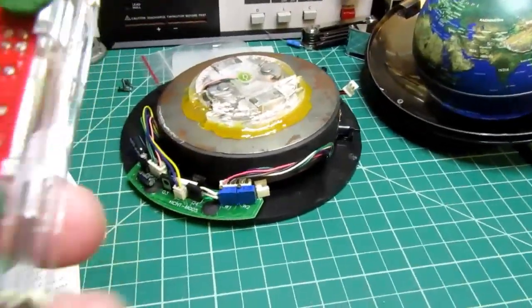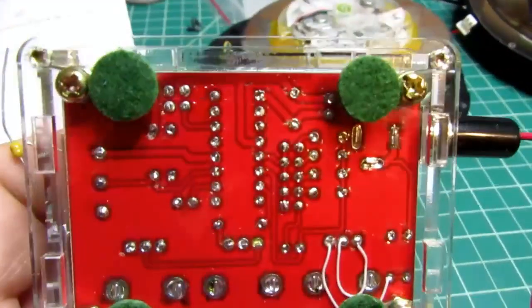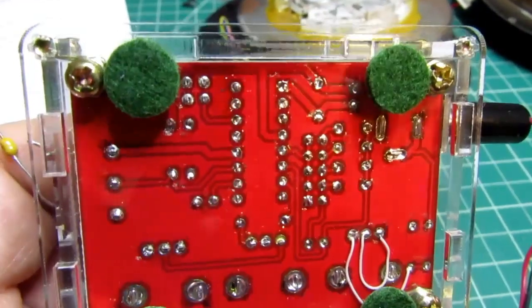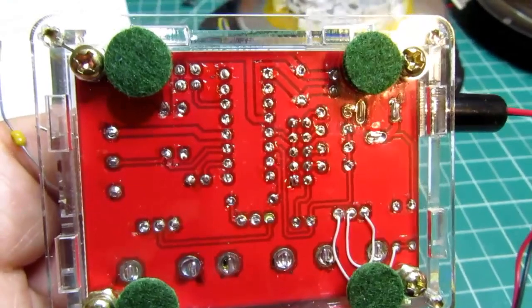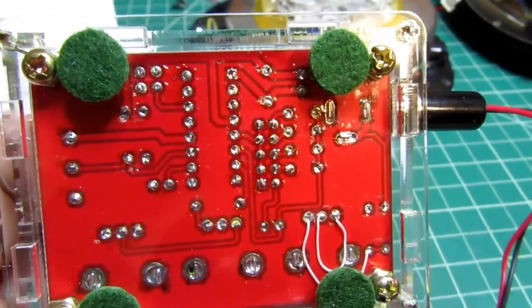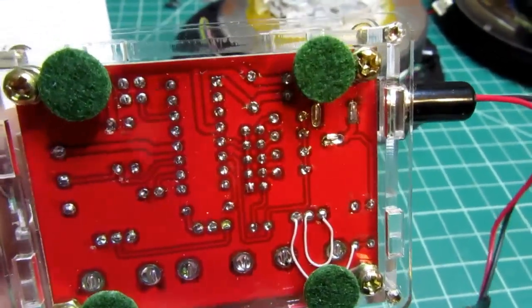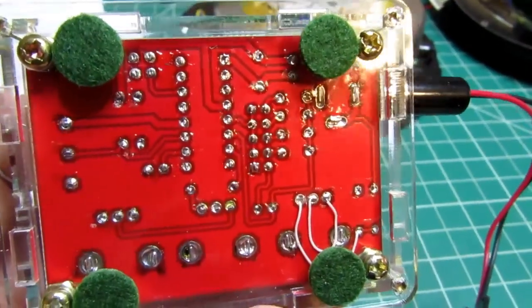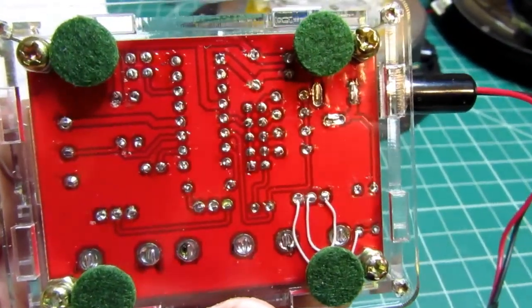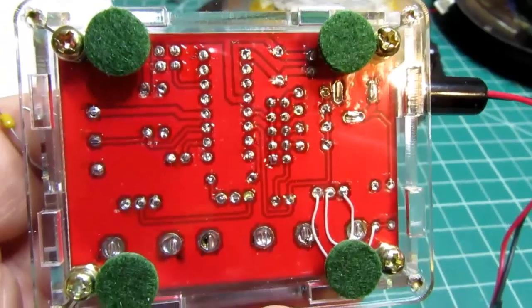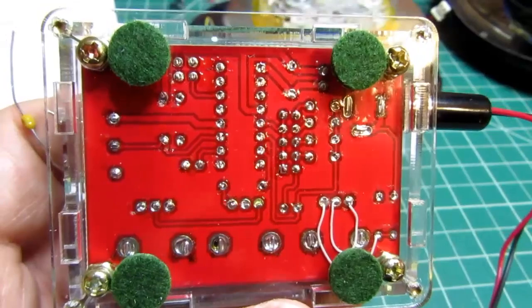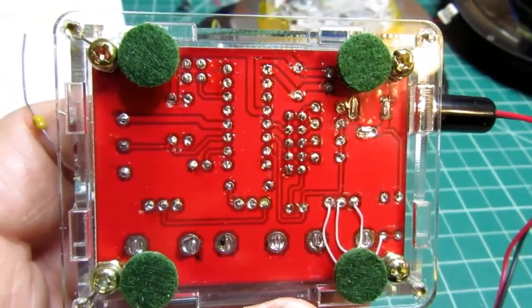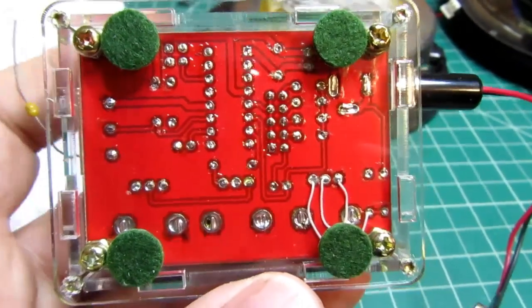That's just a flat out mistake. The other thing I noticed is that the holes on the circuit board are huge, way bigger than they should be for the component leads. That makes it more difficult to solder. Even though I'm a very skilled and experienced solderer, I had trouble getting some of these to solder properly just because there was so much space to fill with the solder. And you could easily overheat some pins if you are a less skilled person trying to do this.